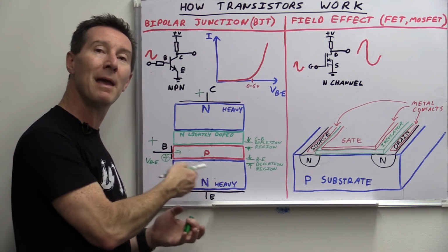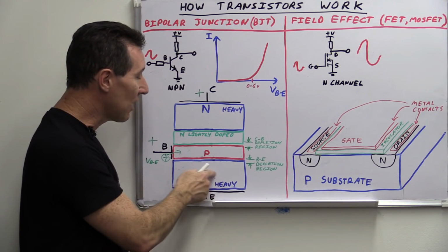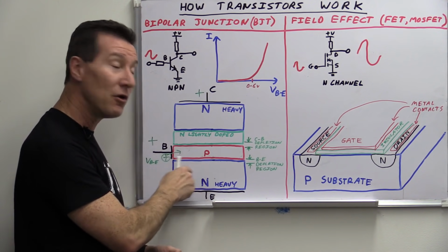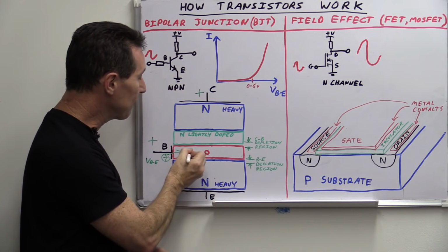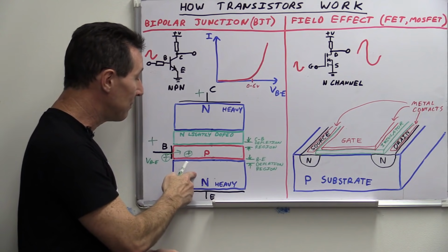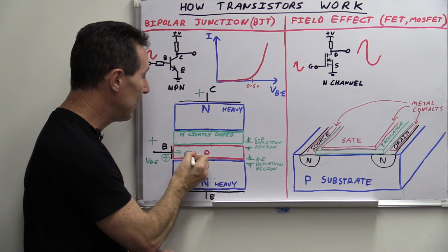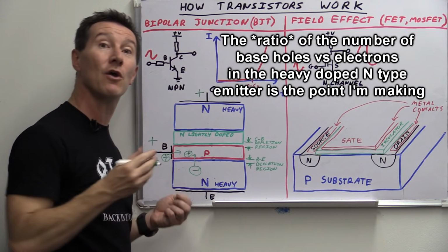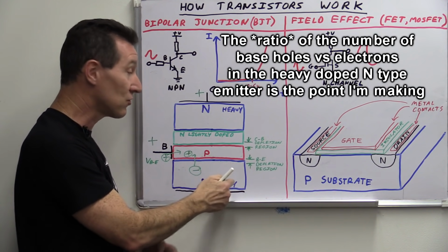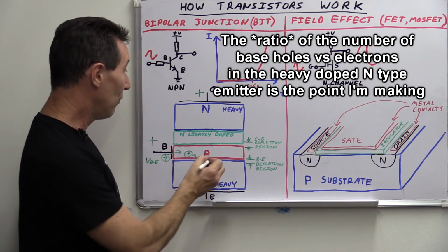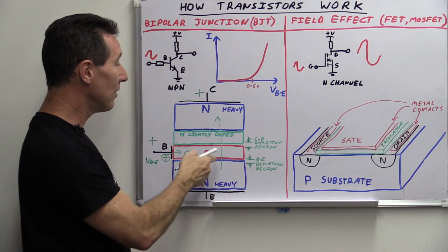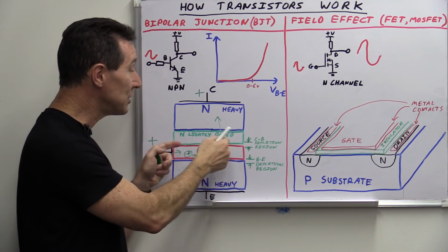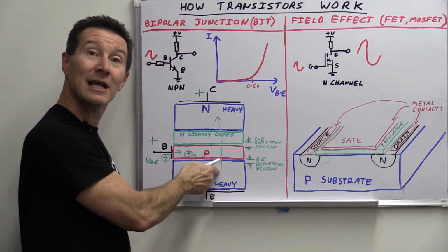It's going to be a small amount of current, but because the N-type material at the bottom is so heavily doped, it's got all these excess electrons, and there are only a few little holes flowing through like this. When electrons flow from the N material up into here, there are millions of them, but only a few of the holes coming over. So where do the rest of these excess electrons from this heavily doped N-type material go? Well, bingo, straight up like that, because there is a higher potential differential voltage in this region here. It attracts all of those excess electrons.